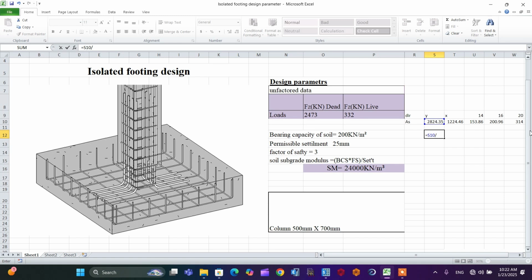This divided by this data, you get the total number of reinforcement for 1 meter width, that is 8.99, okay, 9 plus 1 which is 10. So you must add 1. So for 1 meter width in Y direction, the total number of reinforcement is 10, with a diameter of 20.